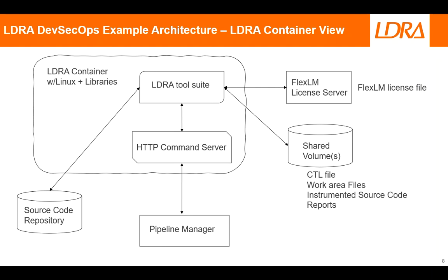LDRA tool suite needs to be able to access the FlexLM server to check the license when analysis is performed. Therefore, the FlexLM location and the IP address need to be in the range specified and accessible by the container. The shared volume is the location where all the results of analysis, instrumented files, and the reports can be stored and displayed.